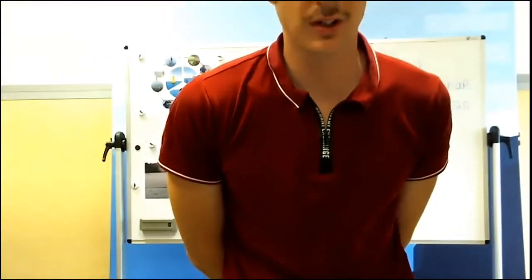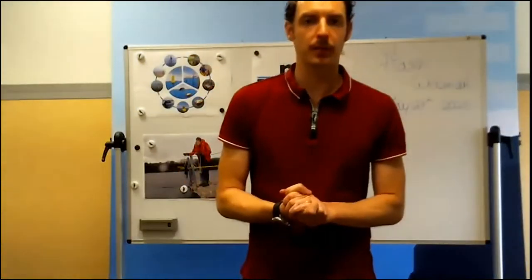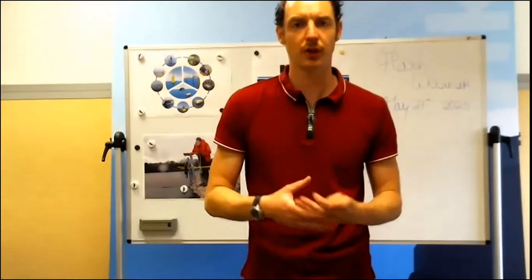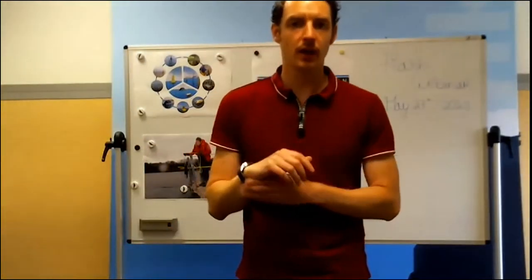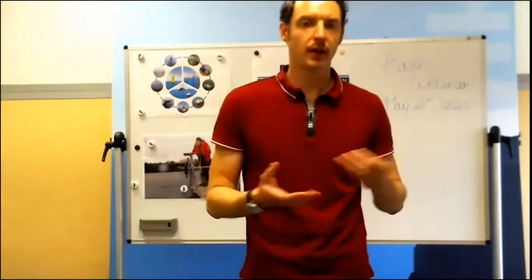And with regard to the question of how long the instrument can stay without cleaning, this is extremely dependent on many parameters. What type of area is it? What type of water? Is it brackish water, salt water? What is the temperature of the water? What is the intensity of the fouling in the area? So in that case, the duration can be more or less long.